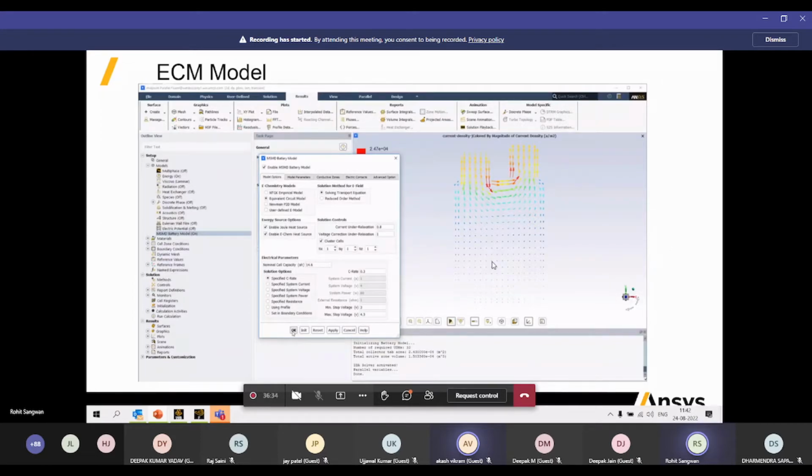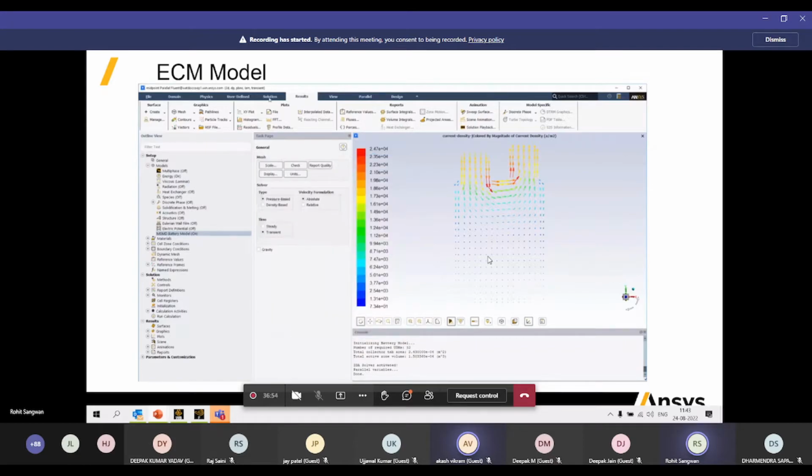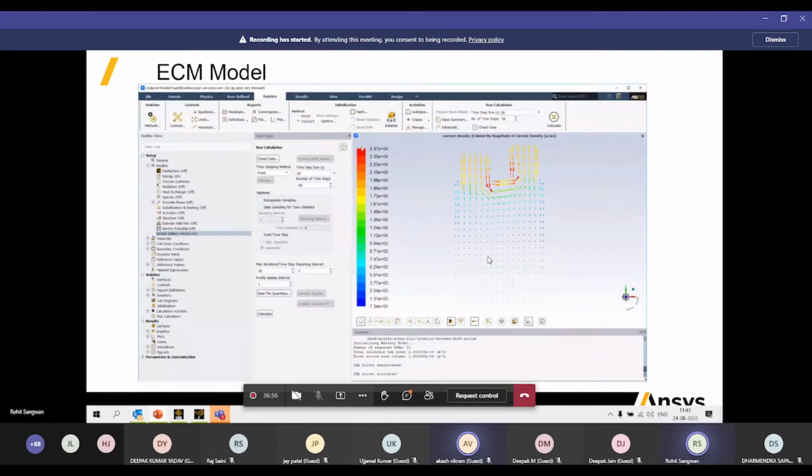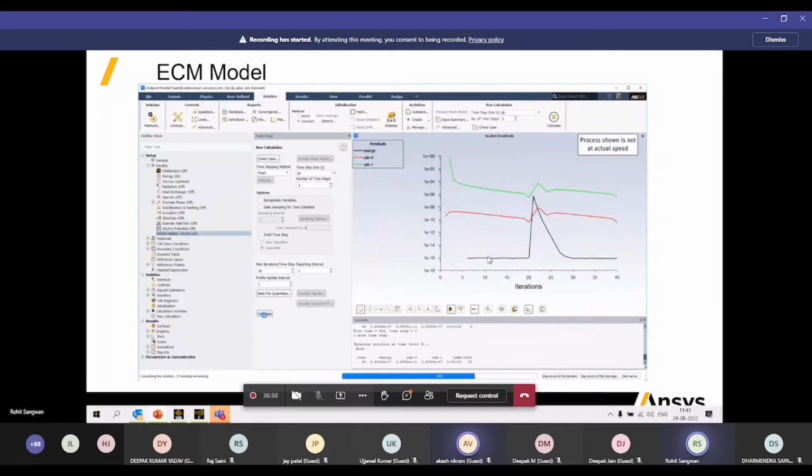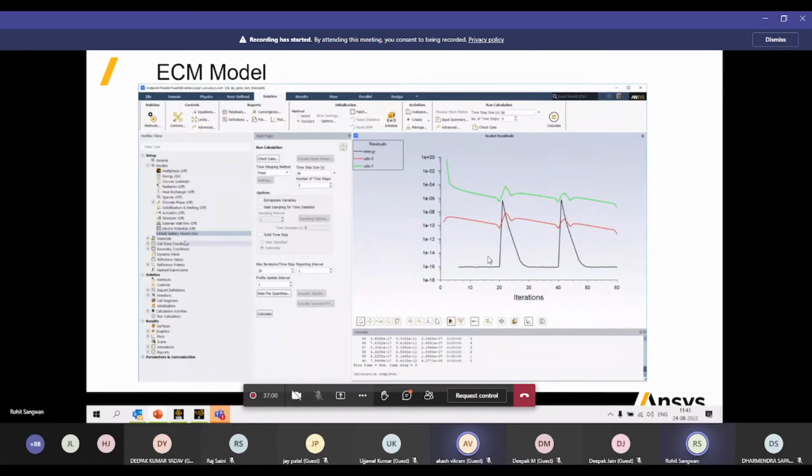To efficiently use this option, we need to have reference potential fields as a starting point for the domain. We can obtain them by solving the problem for only several time steps using the direct method. Then we can switch the solver to the reduced order method and continue the simulation. I'll reinitialize the problem and then run the simulation for 3 time steps. Now I can enable the reduced order method and continue running the simulation for the remaining 47 time steps.